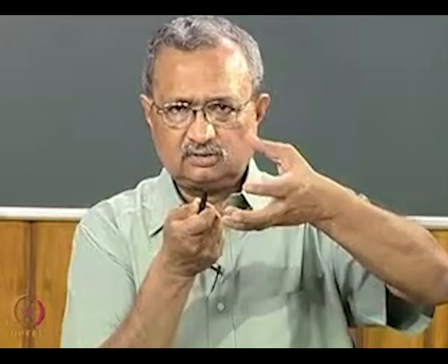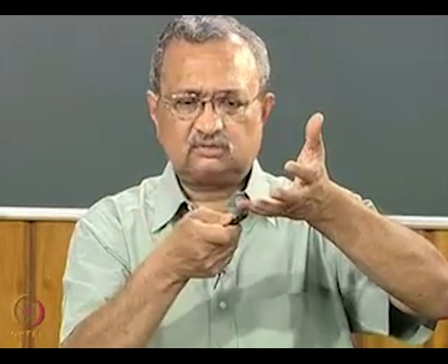Brassware polish means that after making the pot or whatever or thali, it has to be put on a shaft, and it rotates. One person pulls a thread to rotate that thing, and another person sitting opposite holds a knife in hand and chisels out the layer, so that it becomes polished metal. When the brass ware is moving and he is touching it with the blade, that cutting knife, one layer is chiseled out, and by that it is polishing.